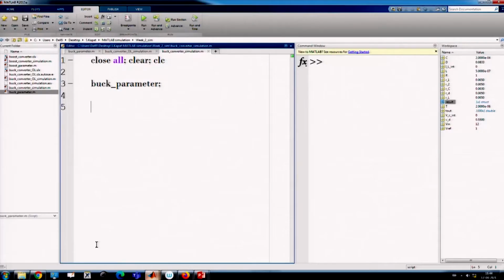Now, we want to take this data, it is there in the workspace. So, we want to create t equal to result.tout, that is our vector that we have discussed, that the structure consists of one time vector. The other, signals, is again a structure, and each signal structure has different values like different channels.